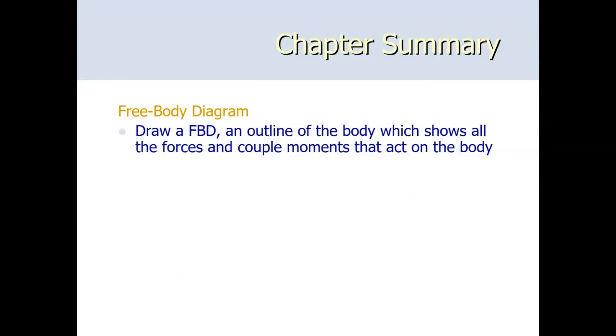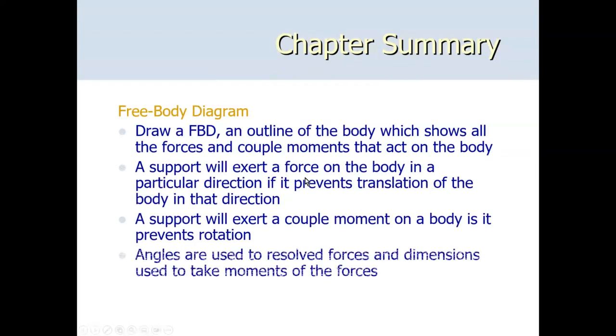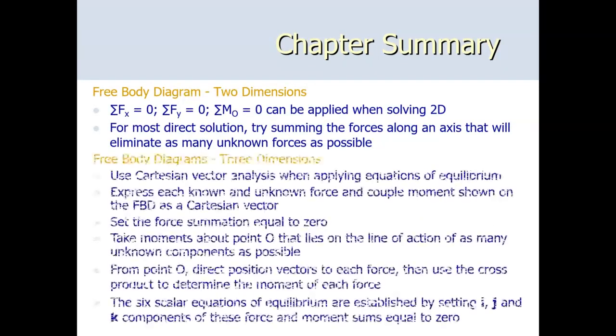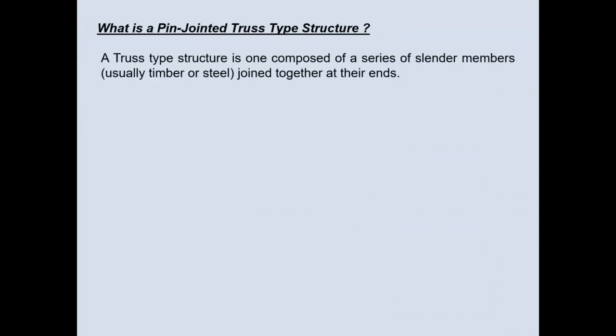So in summary, we learned about the friction forces. The most important part of this summary is that for a rigid body object, you have to consider the offset in how a normal force develops on an object. It doesn't necessarily go through the center of gravity. When you are dealing with a particle, yes, that's true, but with a rigid body, you have to account for the rotational effect. So that brings us to the summary of the friction chapter.